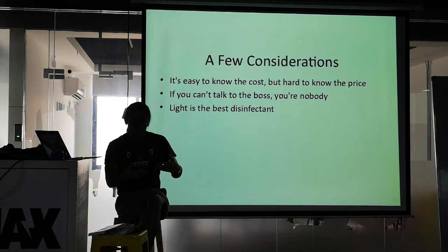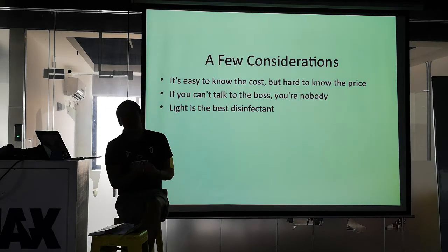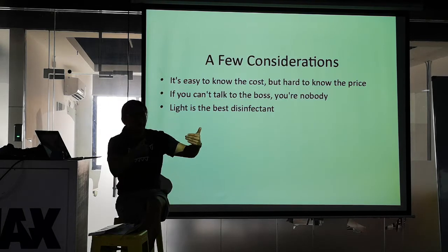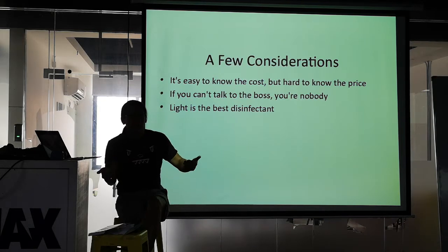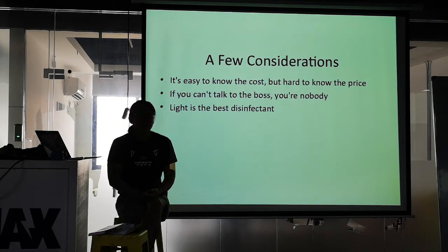You need to look at things like, are they going to do DFM for free? Do you get tooling revisions for free? Is there a line fee that they're going to charge you to set it up? If you have your parts come in, you're scheduled to produce on July 15th, but then there's a customs issue and you have to do it on July 20th, they're going to charge you $200 for a line down fee, right? Because the problem is they scheduled you to run that day, that part's missing. I know it's not your fault, but that line isn't generating revenue that day, right? And so a lot of times there's these little details that are sort of implicit in different quotations.